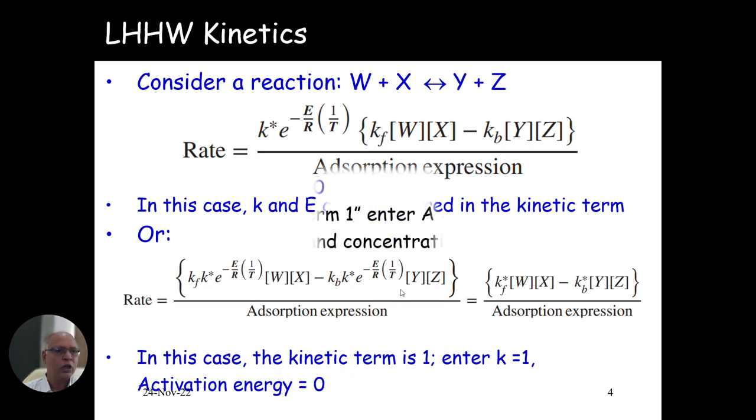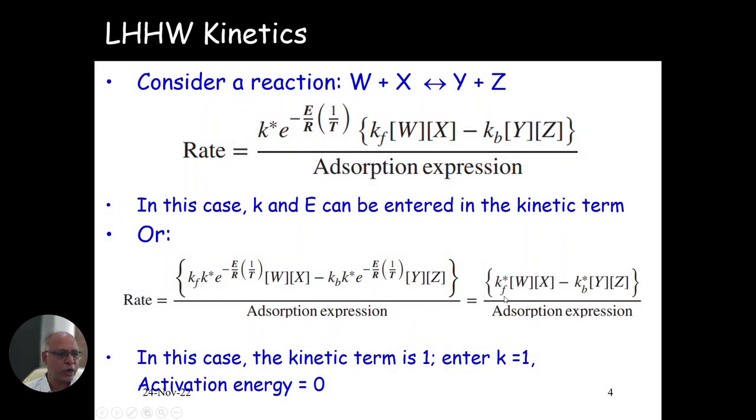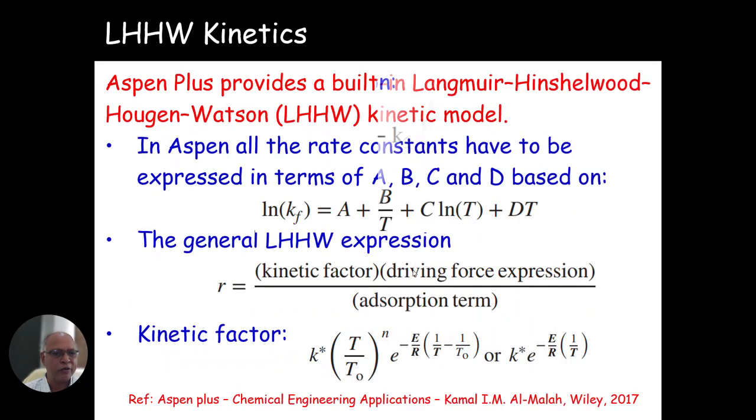But now, we have already addressed this form. Now we need to address this. For example, if you put your rate law in this form, define your kinetic term like this. This is done separately. Now when you go into your adsorption term, whatever value of Kf that you have, you need to take the logarithm as per this equation and calculate the values of A, B, C, D and enter the values of A, B, C, D, right?